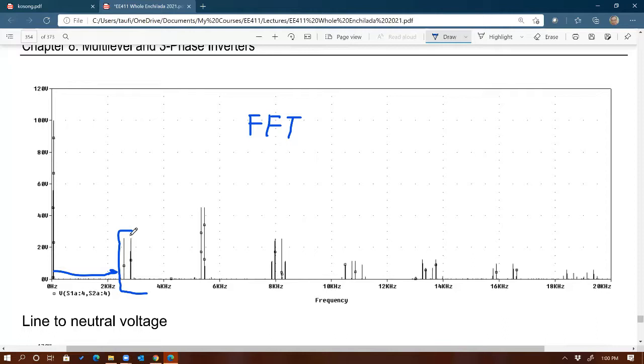Take a look at what happens if you do PWM: further out, right? It's around the switching frequency, depending on the switching frequency, right? So that's actually the same as the switching frequency, sidebands. These are called sidebands noise. So it's around the switching frequency. And switching frequency in this case, I'm guessing is 2.5 maybe. Oh no, I don't remember. Oh, we can check.